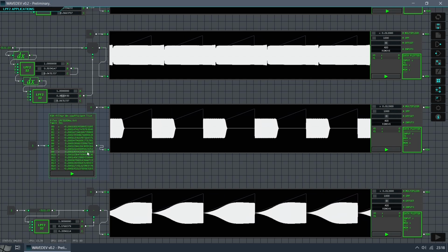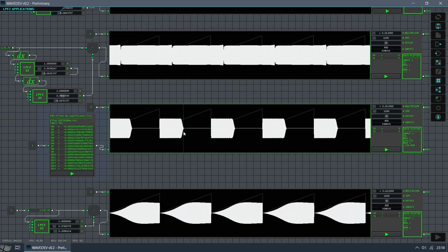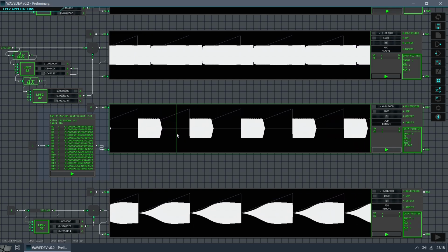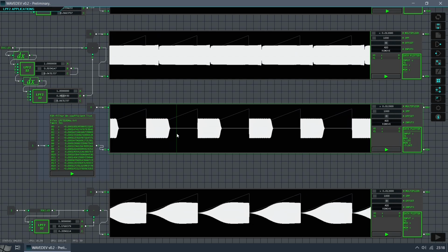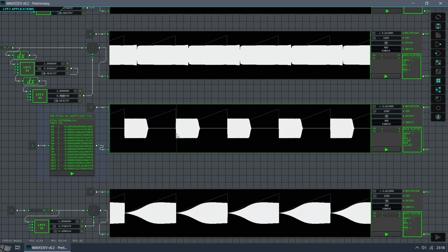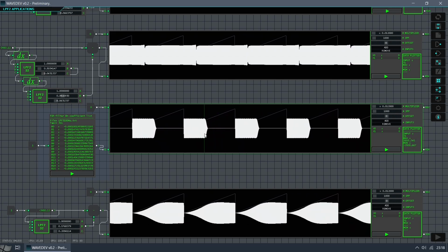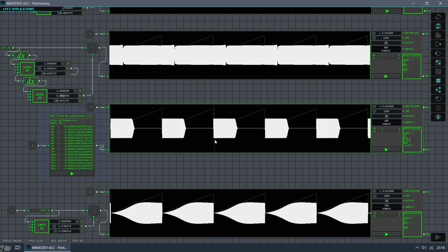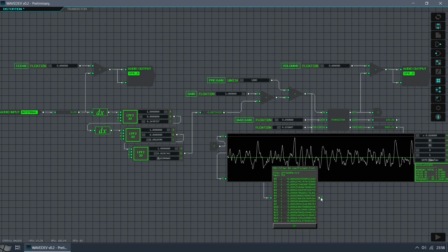It is calculated for a cutoff frequency of 3.1 kHz. I estimate that the harmonics of the guitar from this frequency are very weak and barely captured by the sound card. So we can consider anything above this frequency as just high-frequency noise. I'm going to apply this filter right before the amp.